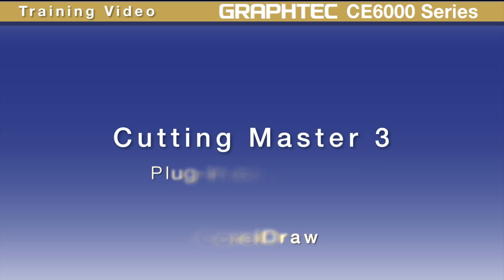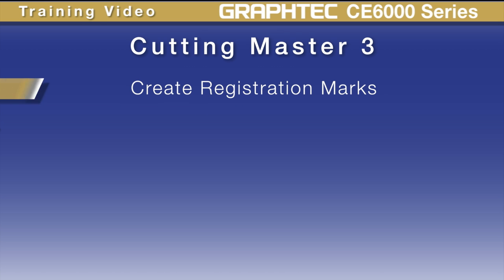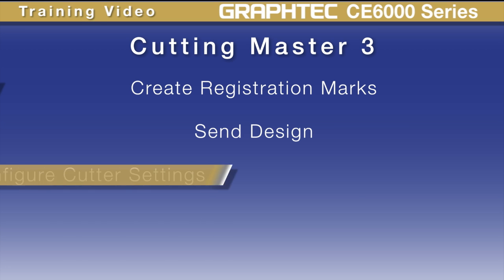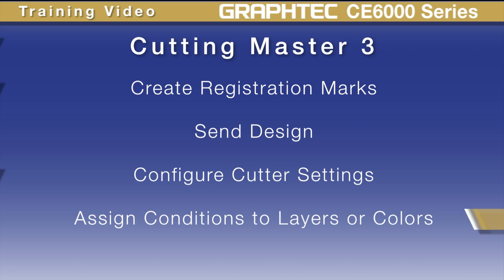The Cutting Master 3 application does several tasks. After creating a design in Adobe Illustrator or Corel Draw, registration marks for the print and cut process can be placed on the job design. The design can be sent from Adobe Illustrator or Corel Draw directly to the Cutting Master 3 application through the special Graphtec plugin that is added to Adobe Illustrator and Corel Draw. It is in Cutting Master 3 that cutter settings can be configured and adjusted, and conditions can be assigned to specific layers, colors, or whole job designs.